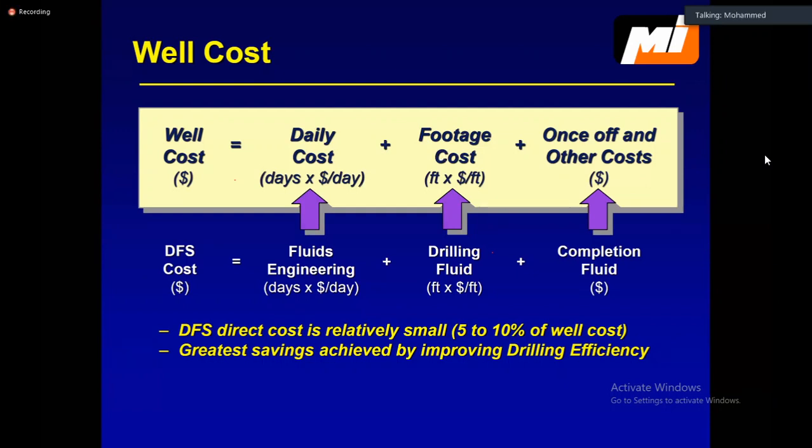I can understand. So, Kakiman, I'm going to start with a question. Actually, even in Kurdistan, during drilling, we encounter shale formations, and according to some laboratory experiments that have been published, we have to saturate the mud with ions. So it's not to change, it's just to prevent the ion exchange between mud and shale formations. So what do you use in HKN for preventing shale swelling and shale collapse, to saturate the mud with ions? Which kind of salt?